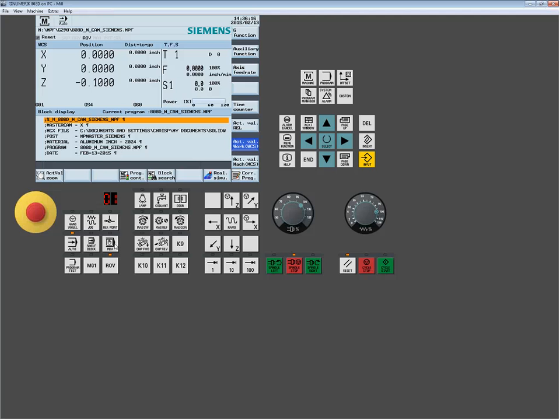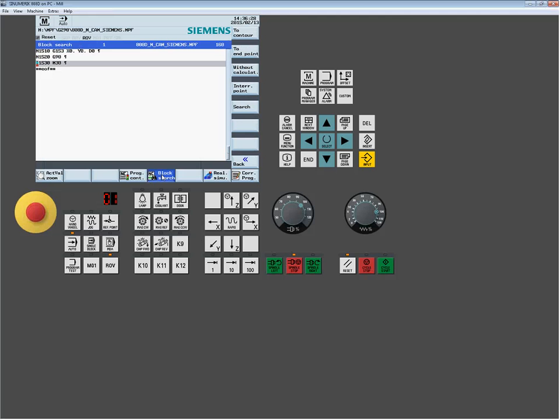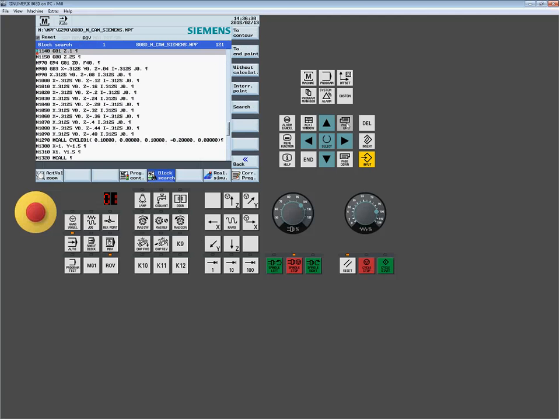That's what the D0 statement does. It puts it into a rapid mode and tells the machine to go away. Any of this stuff, if you're not familiar with it, I certainly recommend going back to my earlier 808D milling webinar I did a few months back. We go through all these commands in a lot more detail because we actually write a live exercise.